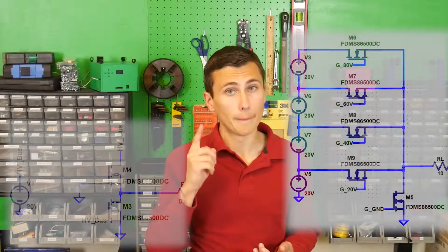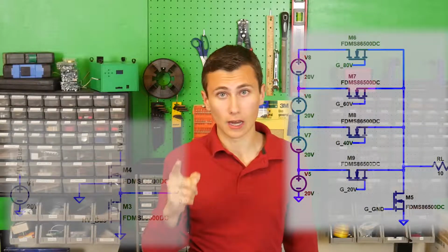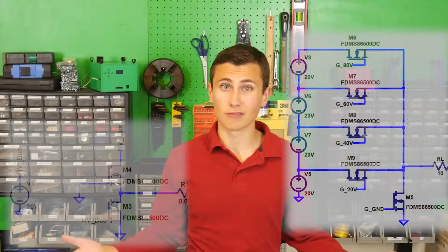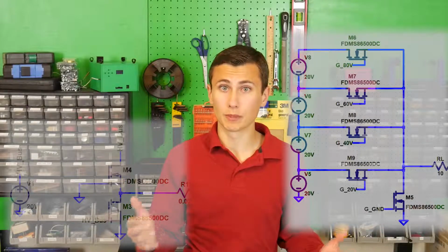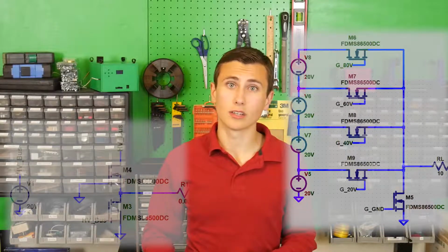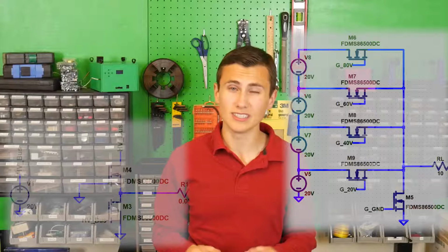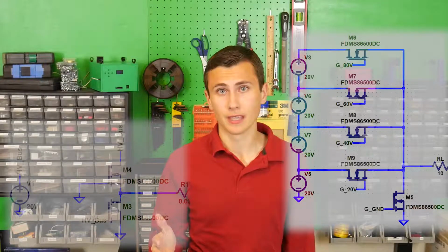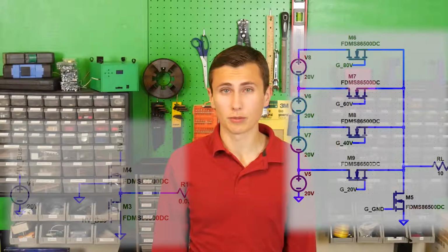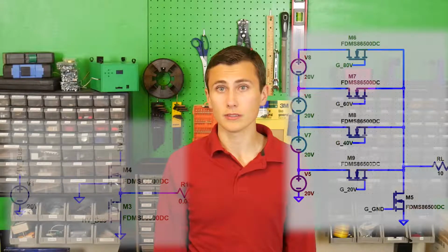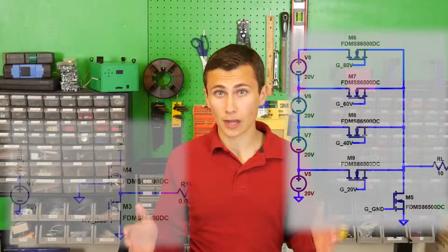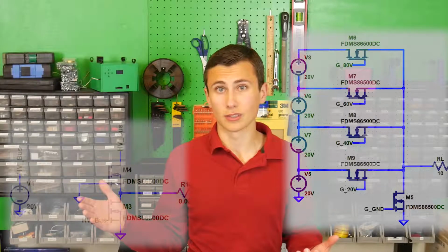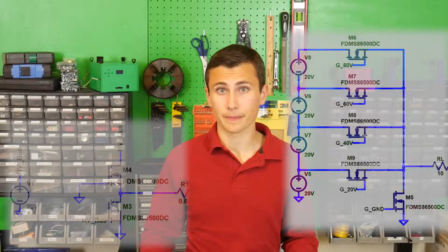May be decreased is a careful choice of words, since not all high-frequency noise on a board can find a coupling mode to escape the board, and it's very easy to create accidental antennas on a PCB just perfect for radiating this energy. Generally better to design in provisions to reduce electromagnetic interference or the radiated energy coming off of a board, even if you don't expect them to be necessary for a particular signal, just in case.